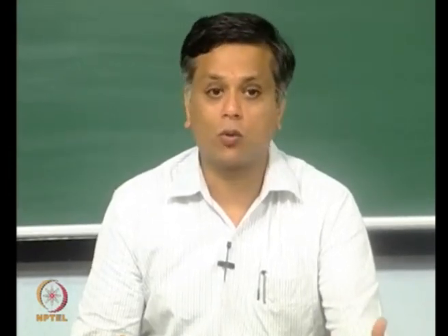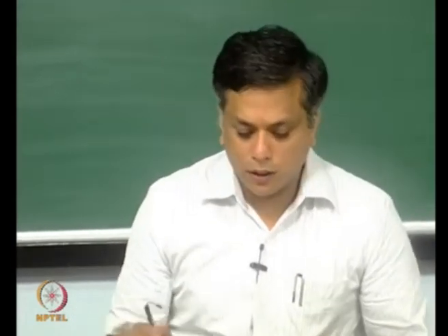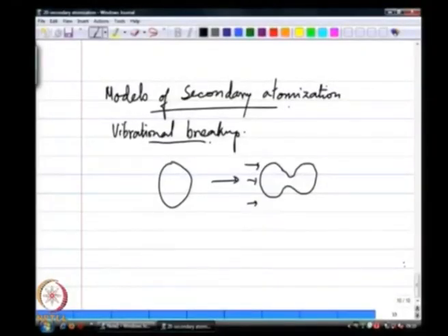Good morning, welcome back. We are going to extend our discussion of secondary atomization, look at a couple of different modeling approaches, and then look at a generalized modeling approach that you can use not just for secondary atomization systems, but beyond that. The simplest of the breakup regimes for secondary atomization is the Weber number based model, and the first of those is the vibrational breakup regime for Weber numbers about 0 to 10.